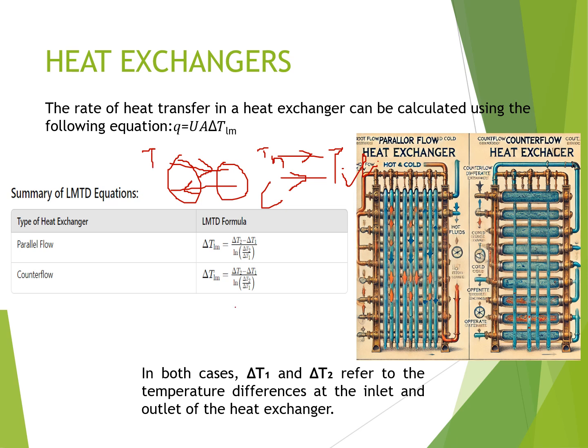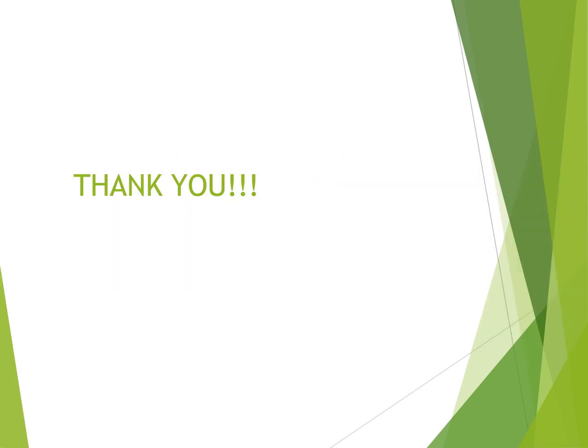So this is the LMTD, that is your logarithmic mean temperature difference. In this way we can calculate the overall heat transfer occurring in a heat exchanger. This is similar to our convective heat transfer formula, and here U is the overall heat transfer coefficient.